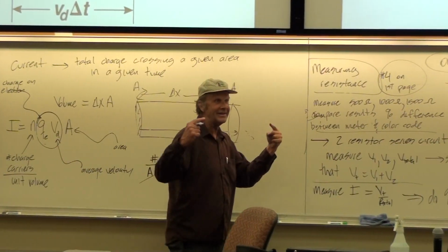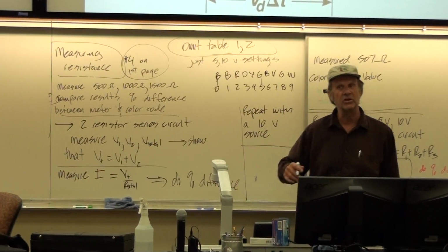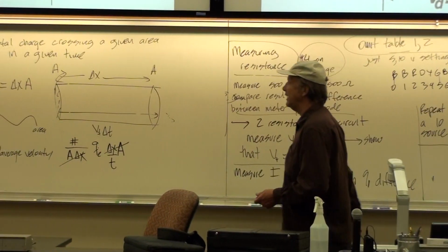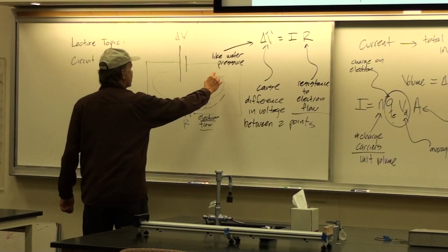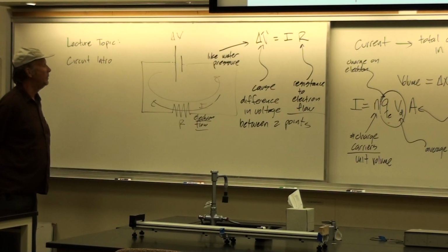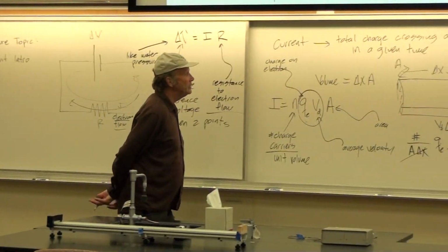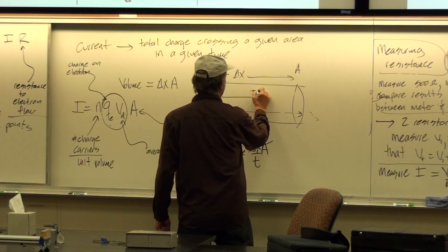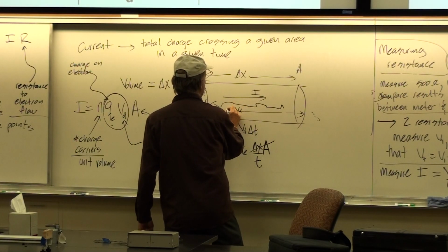And so why have two negatives in there when you can just cancel them out and say, well, this is equivalent to a positive charge carrier moving in the positive direction. And so that's the justification for defining the current this way as going from positive to negative, rather than in the direction of electron flow, which is negative to positive. It just makes the math a little simpler, not to have all those negative signs in there. But we do have to realize that when we do that, that current flow in this direction actually means electron flow in the opposite direction.